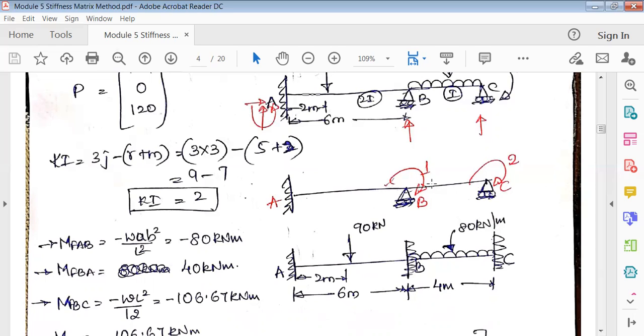So this is 1. Okay, this kinematic indeterminacy is 1 here. Okay, next, similarly in C. Okay, in C, it is restricted in vertical direction, there is a reaction in C, but it can still rotate in the second direction here. Okay, it can still rotate. So here this is 1, kinematic indeterminacy is 1 here, and second would be here.